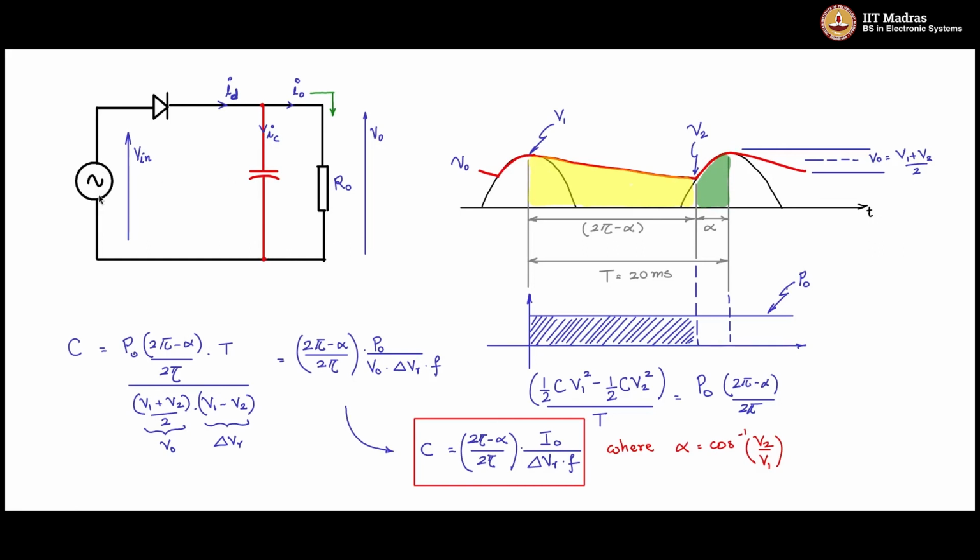The V1 at the input is negative, so it will be V1 minus minus V1, which is 2V1. 2 times this peak value is a possibility that can occur across the diode. So you should rate it greater than 2 times V1.